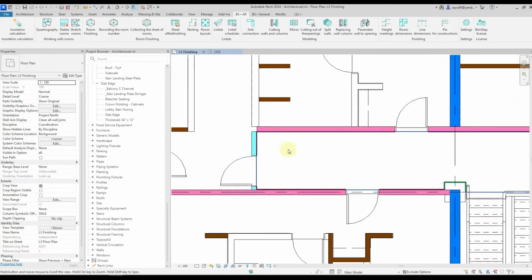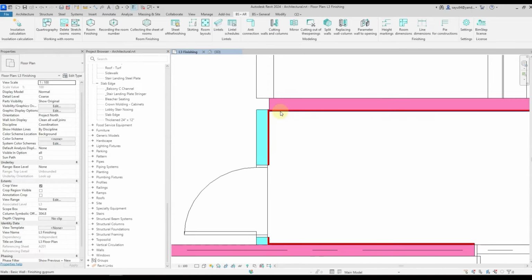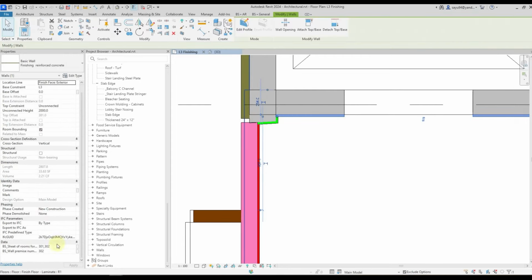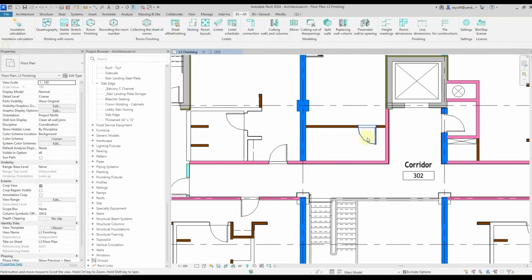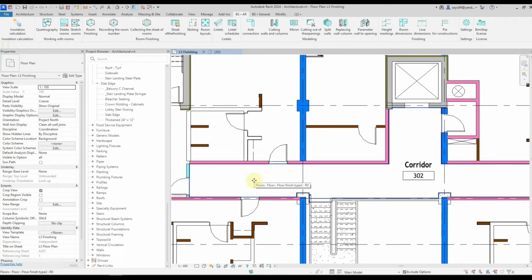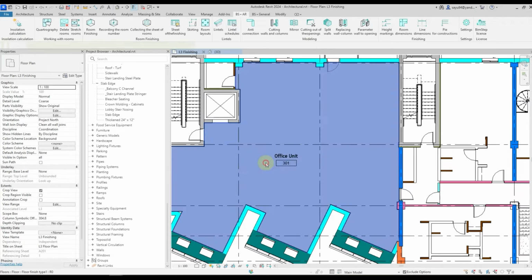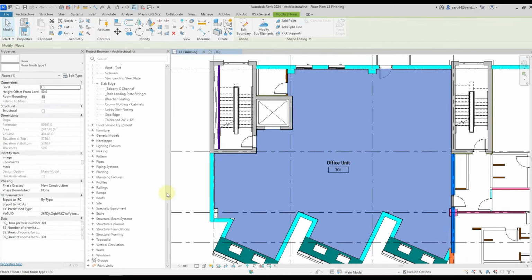Let's see, now if we choose, for example, the red type of finish wall, then in the room sheet parameter we see 301, 302, because that type of wall is in both of the rooms. The same is true for the green walls, as we have them in both rooms. So we comma separated the sheet of rooms in which we have one or the other type of finish. That said, I'll point out if we choose the floor of room 301, we'll have record 301 only, since it's located only in this room.